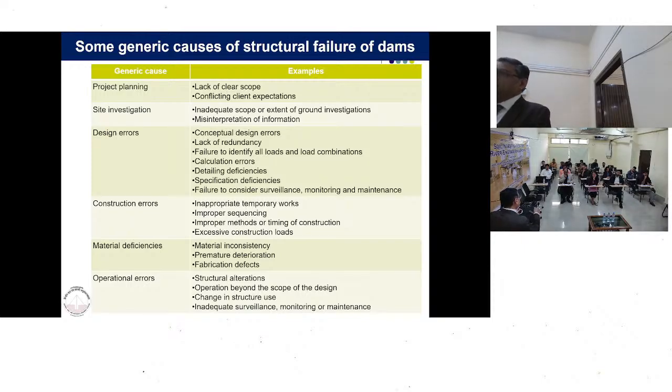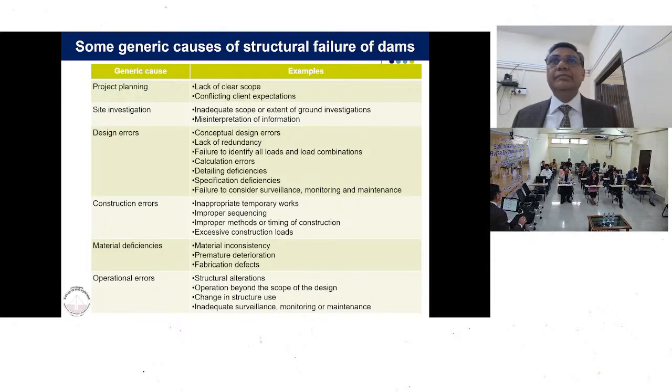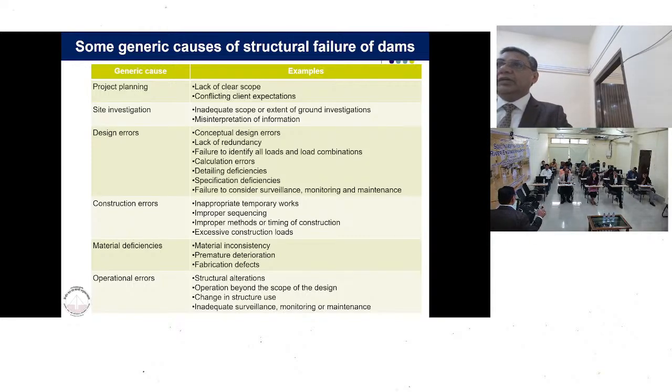Now this geological information is going to come to the designer. Suppose you are sitting as a designer. You get a rock core log which shows a poor RQD. So now what will you say? Why we cannot go for a concrete dam. Initially the abutment was showing that you could go in for a concrete dam also. Now the rock cores are saying that I cannot go for a concrete dam because the foundation is very poor. So now what to do? We'll go for an earthen dam.